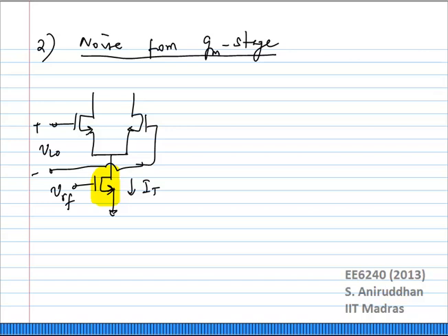Input impedance, looking at which, let me name these transistors M1, M2 and M3. You want to look at the impedance looking into the source of M2 and M3. Okay, what will that give you? Cut off. So you don't have to worry about one of them. But remember that it's a function of time. Which one is cut off and which one is on is a function of time. So is that really the way you want to look at it?